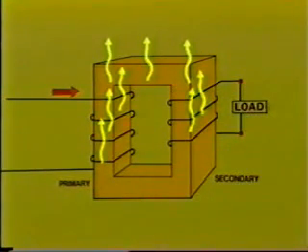These load losses are mostly due to the ohmic resistance of the high and low voltage windings. As you know, load losses are referred to as I²R losses, since they can be calculated by multiplying the winding resistance R by the square of the current, I. So, load losses are proportional to the square of the amount of load current passing through the transformer.